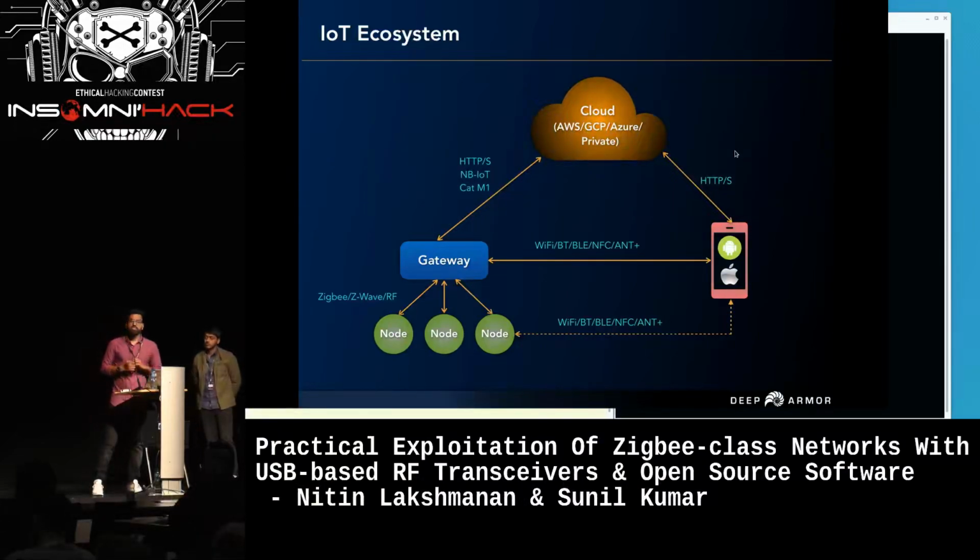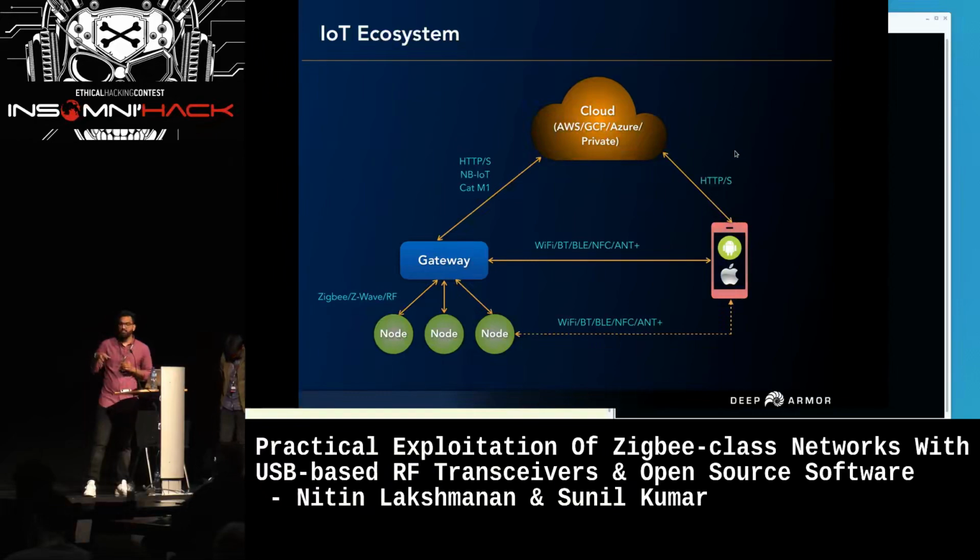In the home automation system, we'll have nodes which collect sensor values like temperature, security alarm and more. At regular intervals, these nodes will send the information to the gateway that is deployed in the house. It will be using lightweight protocols like Zigbee, Z-Wave, RF signals. Once the data is received, the gateway will send information to the cloud through HTTP protocols.